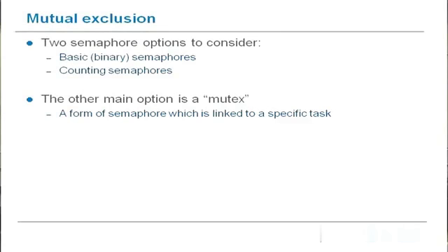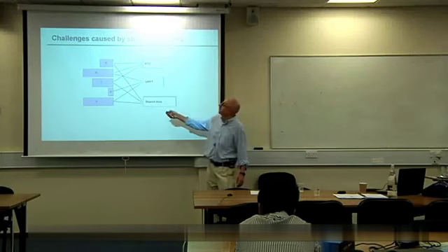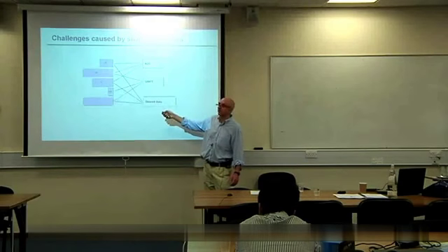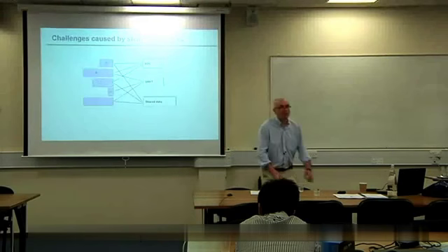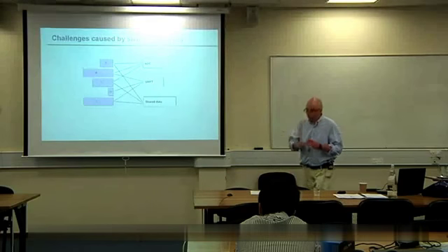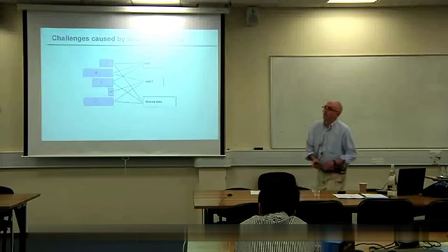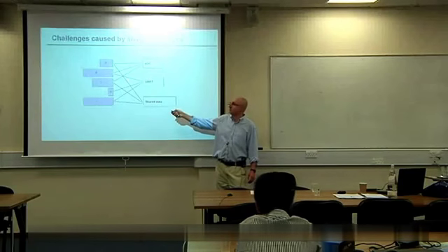If we're going to have any kind of shared resource, we need some mechanism. The first basic issue here: what would be the issues if we had no protection around the ADC? What might happen in the ADC if this task was using it, and then this task interrupted? What do you think might happen? Mid-conversion or something like that, and you could get some horrific data back. Yeah. So this one could have configured it to read from channel 2, say.